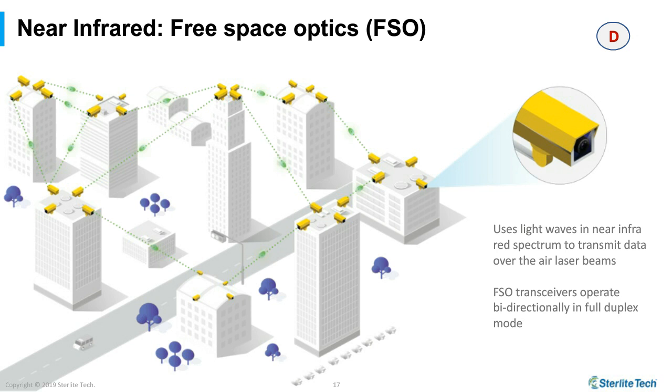And one other thing is that 1550 nanometer also puts it in the class 1M laser category, which is eye safe. Unless you look into the beam with magnified optics, it's actually quite safe for the eye, because the cornea and the lens do absorb it. So that's a very key element here, because laser can conjure up images of a lot of health issues, so it really needs to be brought out here. And again, we're looking at micro radian beam width, and unless you're right in the face of it, you're not going to even see the beam.